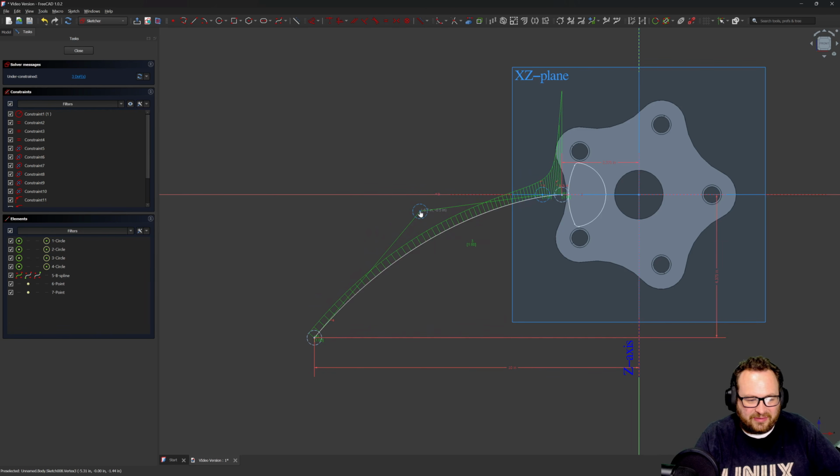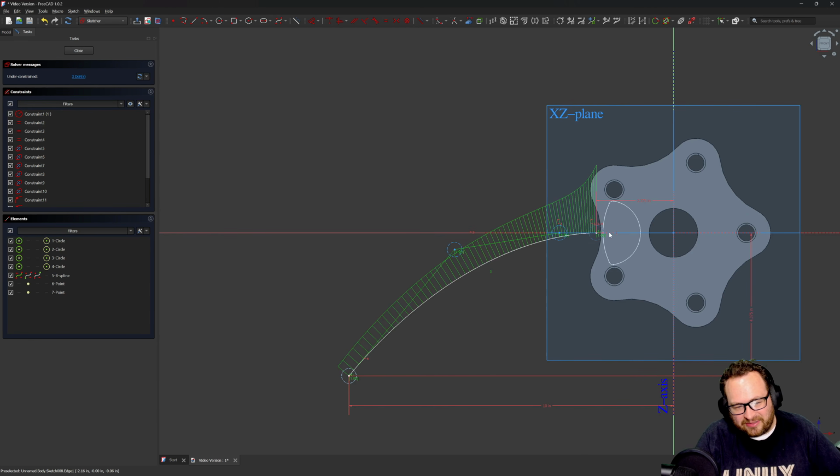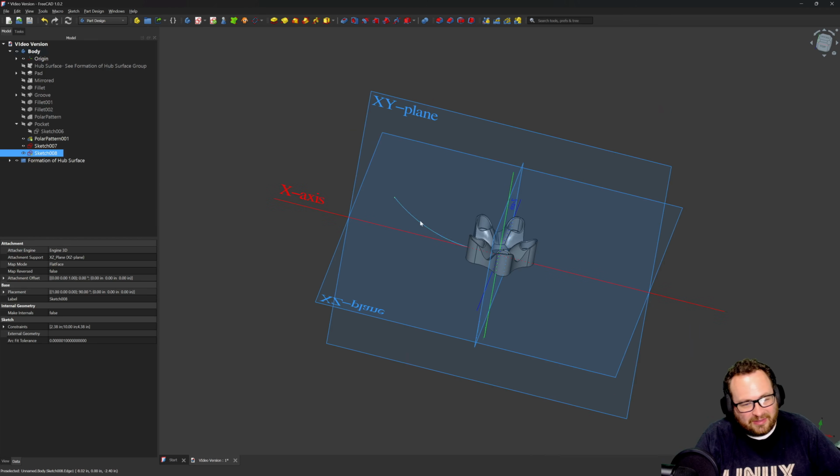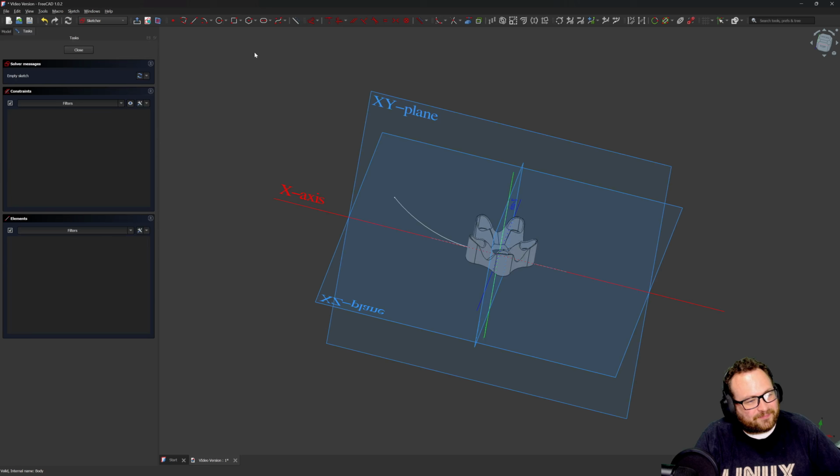And so I can't really move around this endpoint nor this endpoint, and I can just take this intermediate sketch point and this one that I can slide and make kind of a nice non-constant radius path. Let's say that I'm happy with that, right? If I want it fully constrained, I can constrain these center points right here and right here, these guide points, but control points, I should say. But I'm happy with that. We're going to say XY plane.